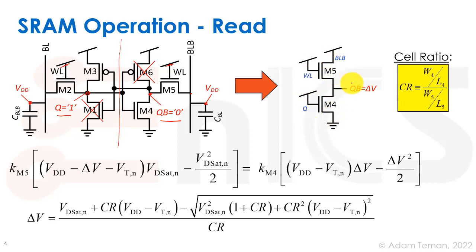We take the schematic and it comes out, as we saw in class, something like this, which is just a type of NMOS inverter that is pulling down its output to the lowest point possible, which we would call the VOL. And it's going to be some sort of a delta V. It's going to be larger than 0.